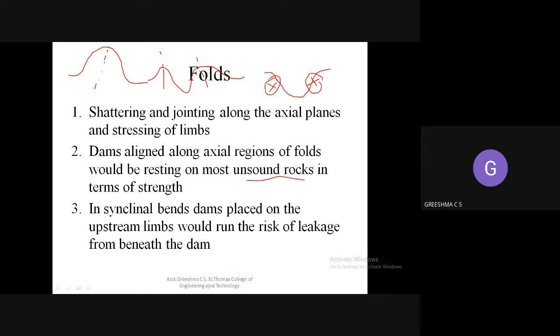So the dam should be aligned properly, on a hard strata. It should not be aligned along the axial regions of the folds. At the same time, it should not be aligned along the upstream limbs of a syncline fold.